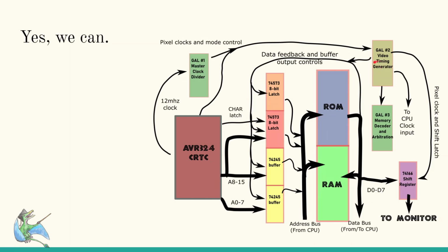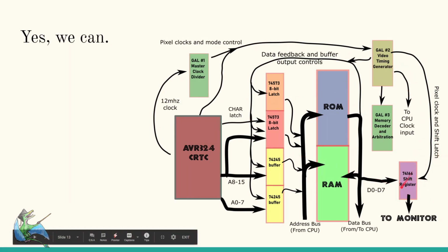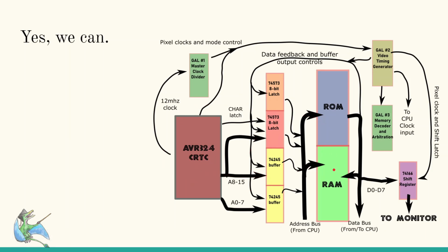On the first tick, where there are 8 ticks for the pixel clock coming down here, we are splitting it 50-50 between the CPU and the CRTC. So effectively, if we're running at the 8 megahertz pixel clock, we're going to run the CPU at 4 megahertz, and the video system gets the rest of the time.